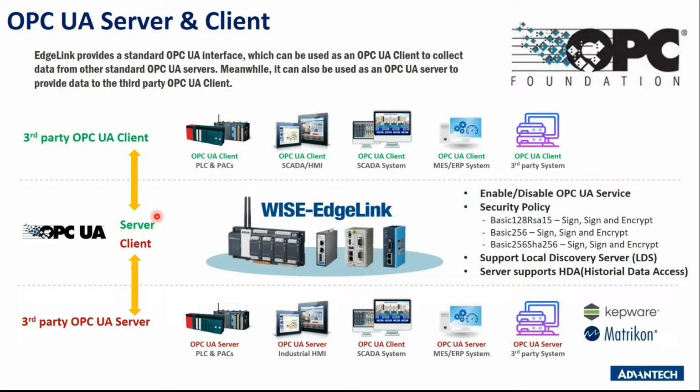So you will see from here, we are doing protocol conversion. The reason is we can do the OPC client and OPC server at the same time. That is one of the examples we are giving, using the OPC protocol. They are showing you that our hardware itself can do protocol conversion, right? So in my hands-on part, I will actually use Modbus to simulate a Modbus server and client for this scenario.